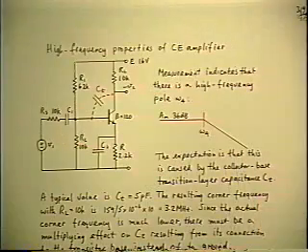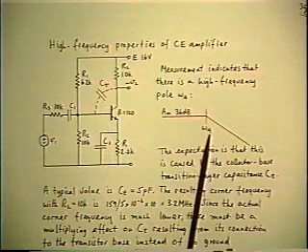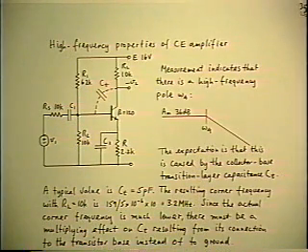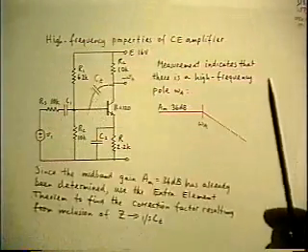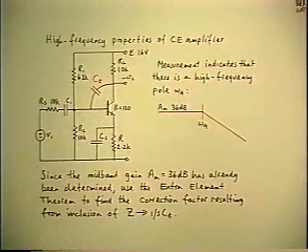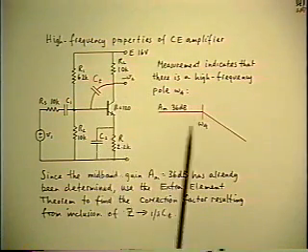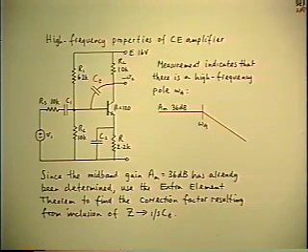So maybe we shouldn't be so quick then to drop the idea that the CT is the explanation of the 47 kilohertz corner. So let's follow up on that now and get the quantitative result and see whether in fact we do get the multiplier effect. Well, this is now an obvious setup for the extra element theorem again, because the CT is one more element we want to put into the model after we've already calculated the mid-band gain, which we thought initially was going to go up to much higher frequencies.